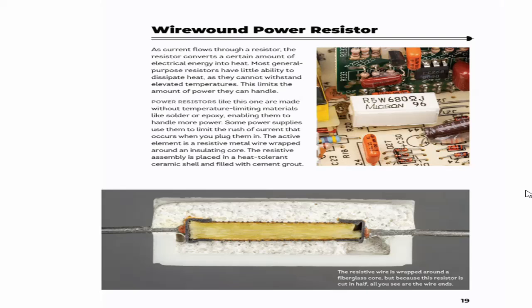Its advantages are it can handle high power, it is low inductance, it has high stability, it is suitable for high frequency applications, and it is cost effective. The disadvantages are large size, limited precision due to winding, potential for thermal drift, and may experience noise and vibration.